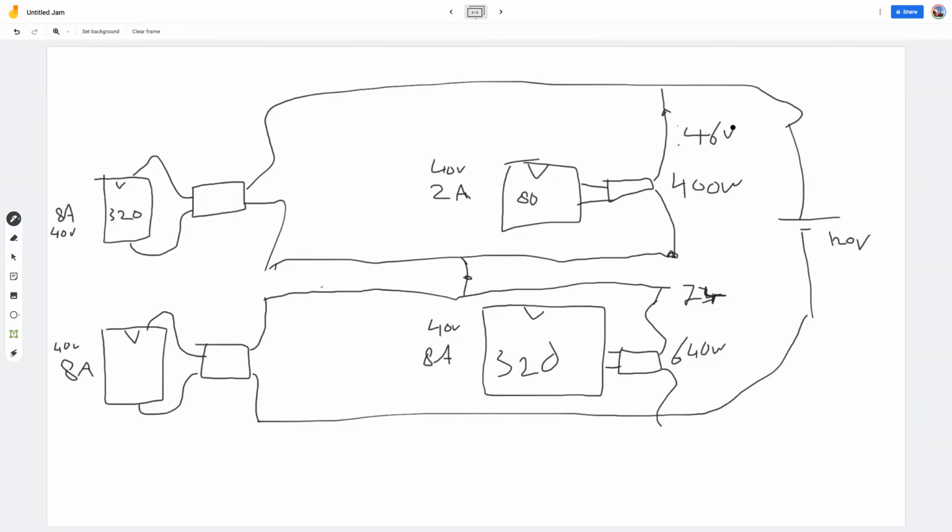Yeah, and I think this is something Tokai did in 2011. I found a circuit of theirs online, and they had 5 MPPTs on the bottom and 4 MPPTs on the top that they paralleled. And then of the bottom 5, one of them was the one that got severely shaded. That way they were even able to balance it a little bit better. I'm not able to find that picture anymore.